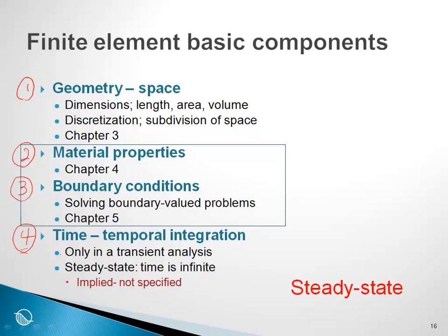Just one last quick comment about these finite element basics. Our human nature is such that we tend to spend most of our time on the things we know the best. And so we often know the most about geometry, and we tend to spend a lot of time on the geometry. But spending a lot of time on the geometry does not do us much good if we don't have a good understanding of material properties and boundary conditions.